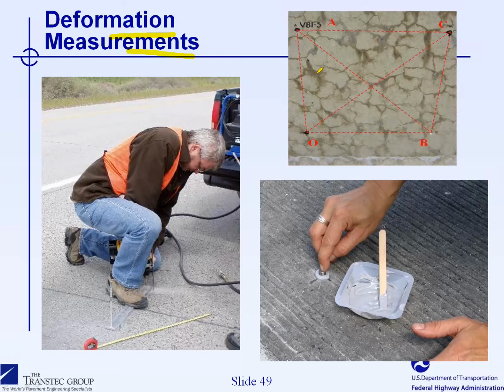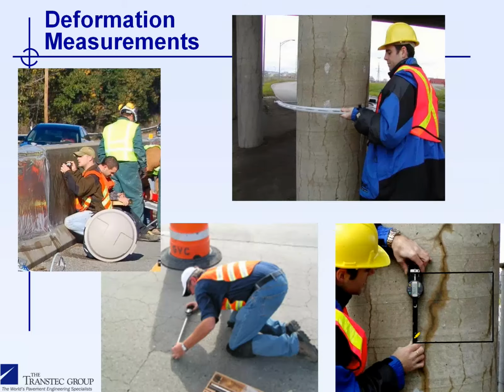Expansion or deformation measurement also can be used. What we have been using and we're suggesting is you can use the same pattern that you use for the cracking index to measure expansion. So this is about 20-inch in dimension. And you can see here Dr. Thomas actually drilling in a concrete pavement section in order to insert a stainless steel pin that will be used to measure expansion, as you can see here in the pavement, using that measuring device.